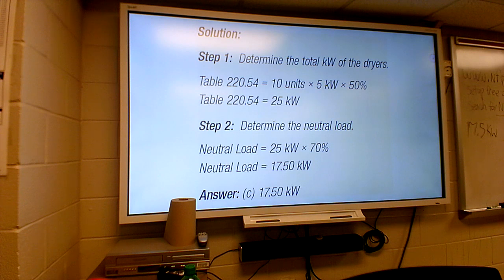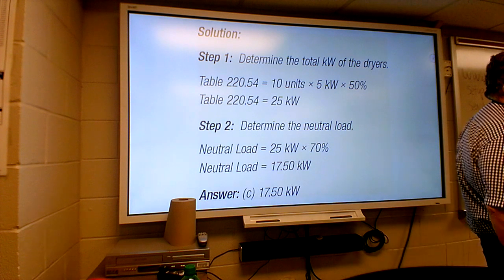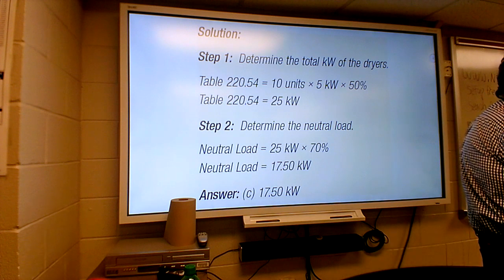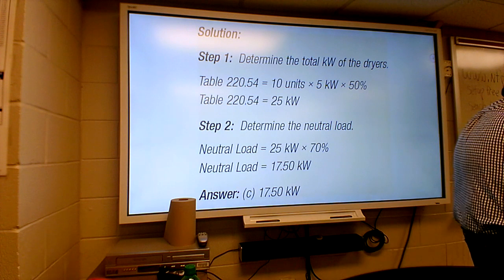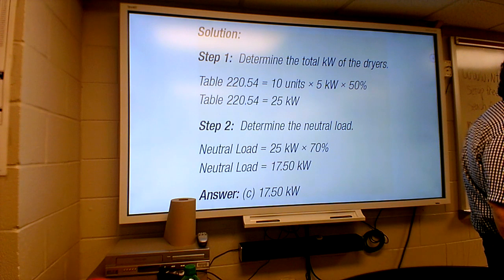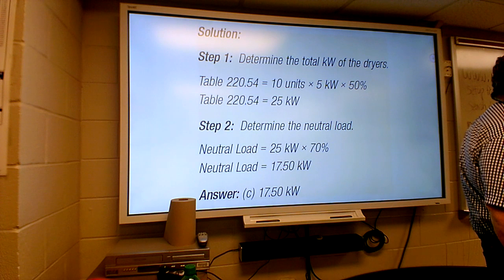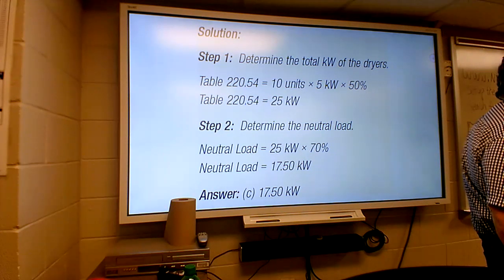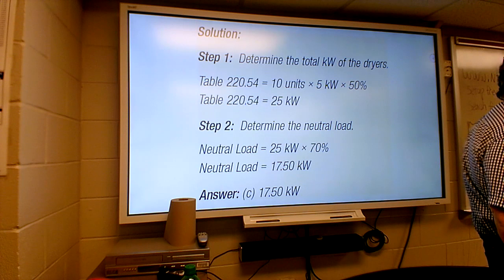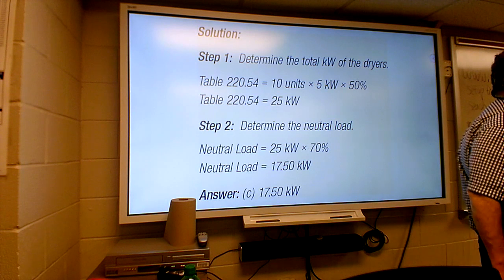What size wire? We want a neutral wire that can handle 73 amps, and we're looking in the 75 degrees Celsius column in your wire chart.